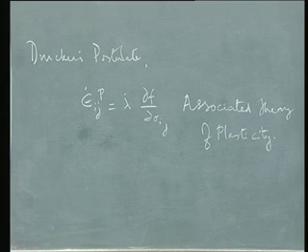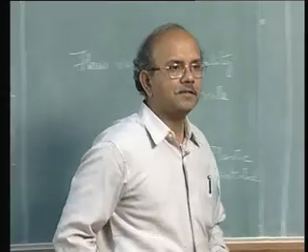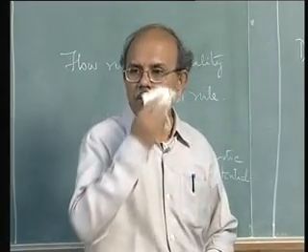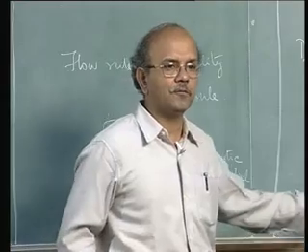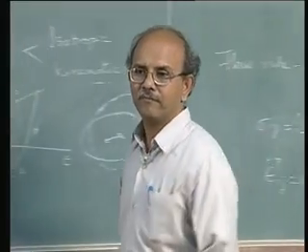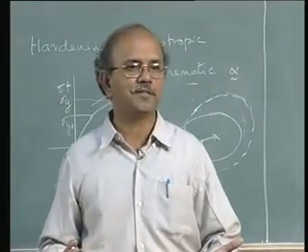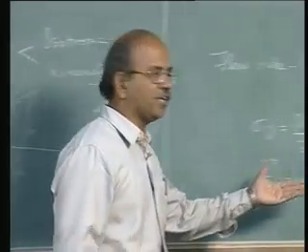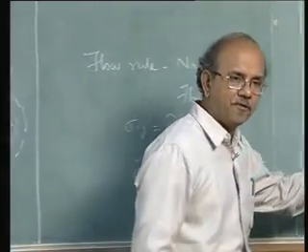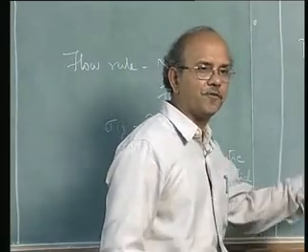Once I say that it's an associated theory of plasticity, then there should be a non-associated theory of plasticity, right? What is non-associated theory of plasticity? Logic tells us that this potential cannot be f. So q is different from f.